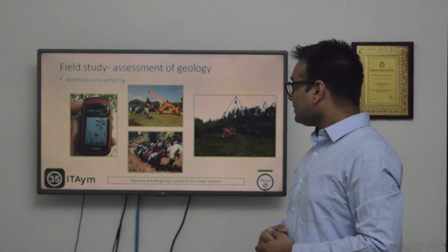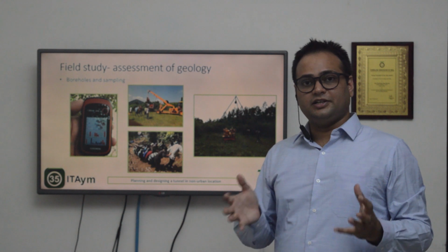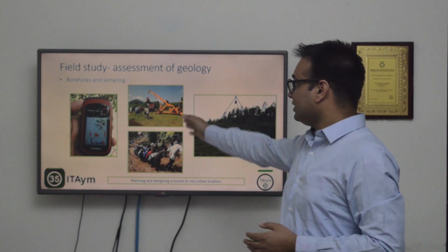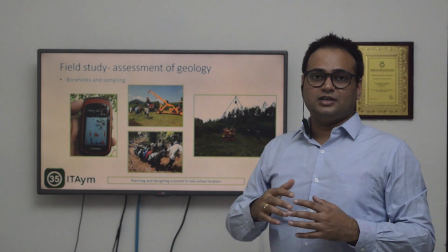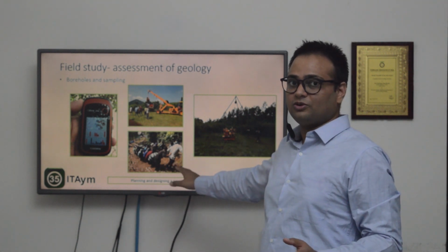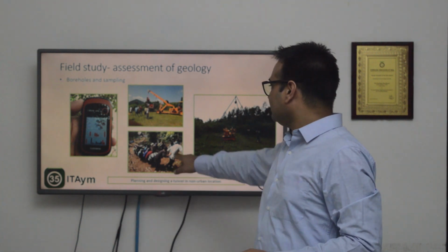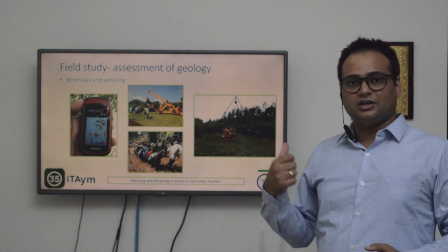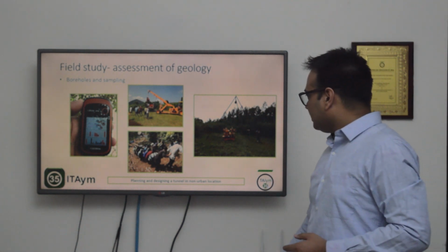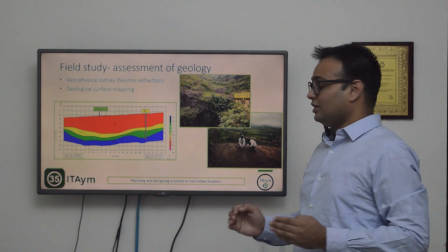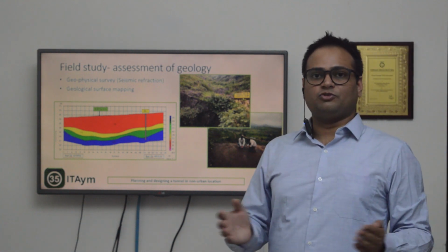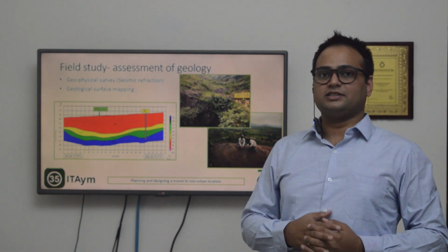After this, the other information that we required for designing a tunnel was geotechnical site investigations and testing. As per the desk study, we proposed a few boreholes that we needed to do. At some locations, it was easy to transport the machines using cranes. But at some locations, they were so remote that the road was not even close to the tunnel, so we had to drag them to the top of the hill with the help of laborers in the vicinity. After this, we did other forms of investigations as well. We went into the tunnels and observed the type of rock and type of joints inside the existing tunnels.